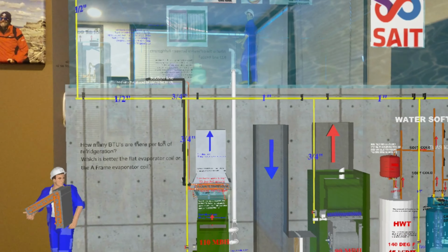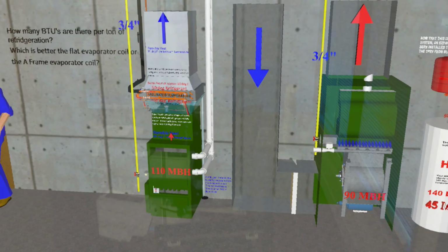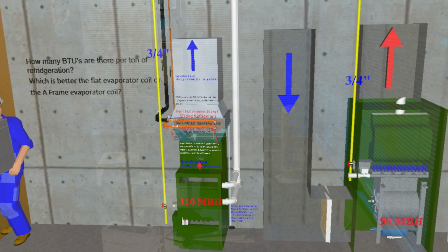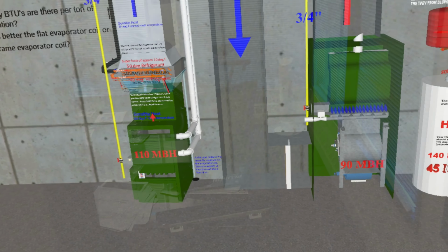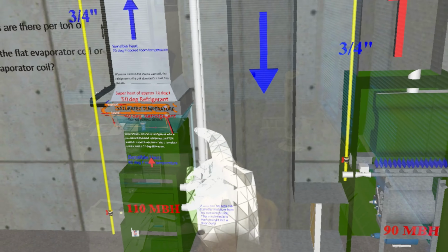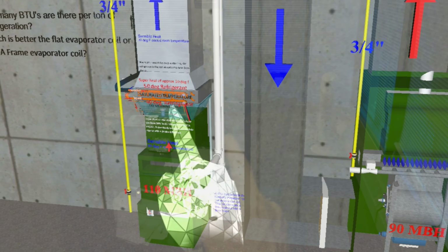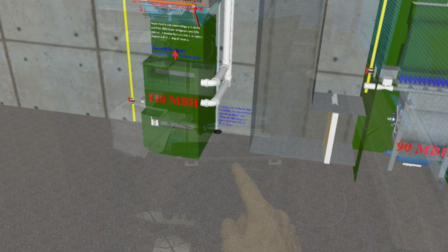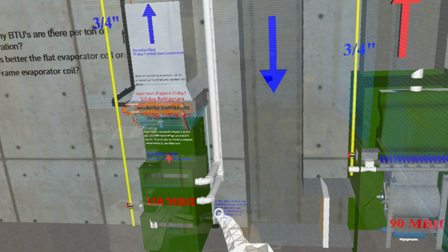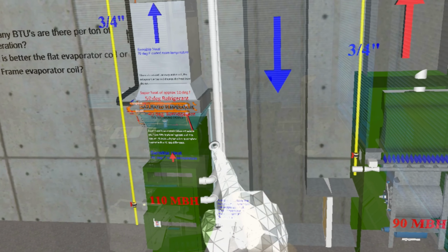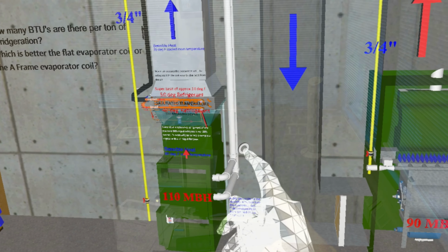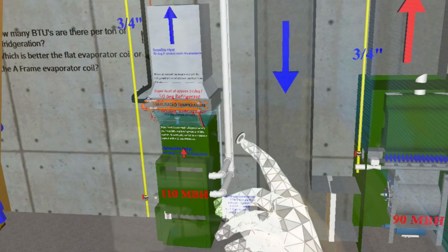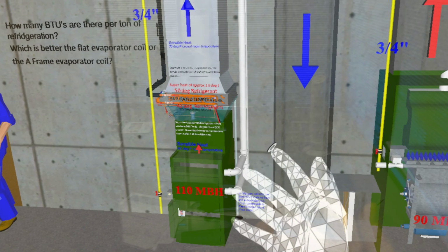Now, some of the questions I've always had when I didn't know too much about refrigeration or furnaces was the drain line that comes from the bottom, the drip pan underneath the evaporator, and it just drops into a P-trap. What kind of water was that? It's called the condensate drain. So typically, it's plain water during the AC or the summer cycle.